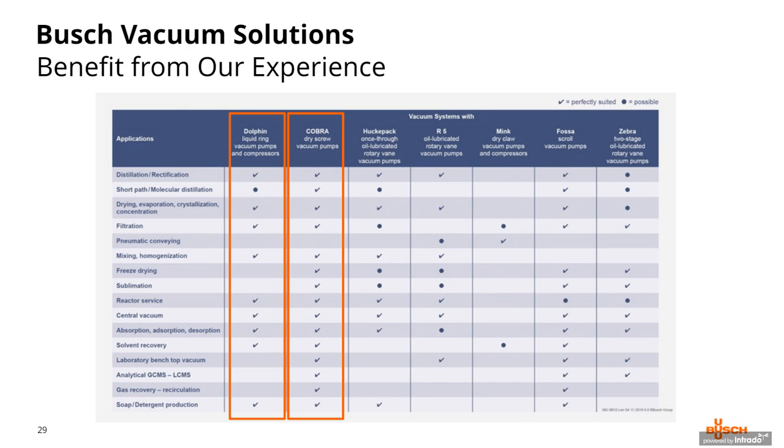I also wanted to mention that the once-through oil-sealed two-stage rotary type is also technology used in this industry. They're reliable and can be used for harsh, corrosive, or sometimes even sticky applications, because the sealing oil is pushed out along with the process. They tend to be reliable over the long term. They have their place in the pharmaceutical industry, but the high cost of the contaminated oil disposal usually makes the once-through oil-sealed rotary type only the best option when the other technologies will fail.